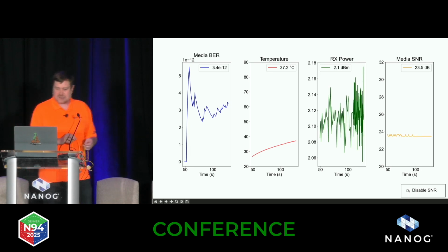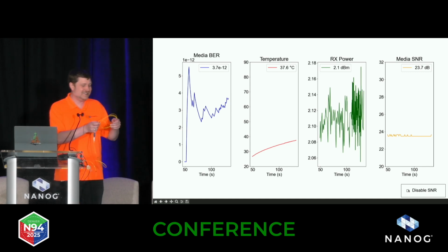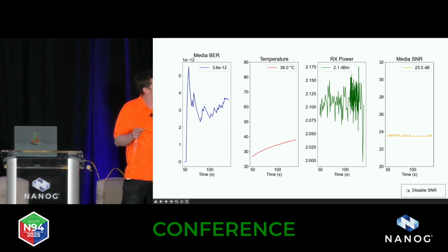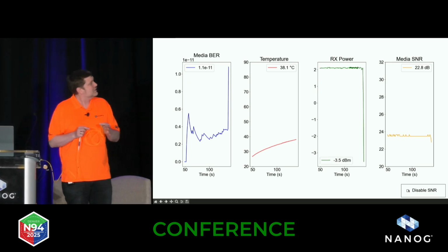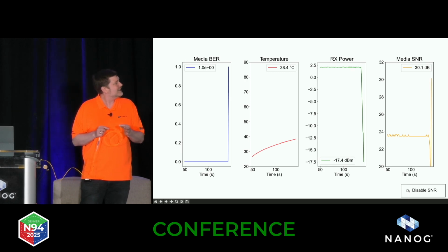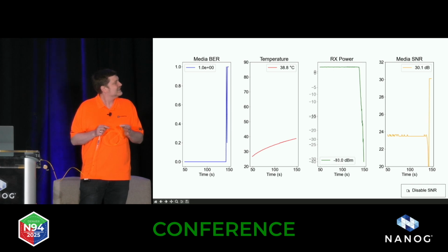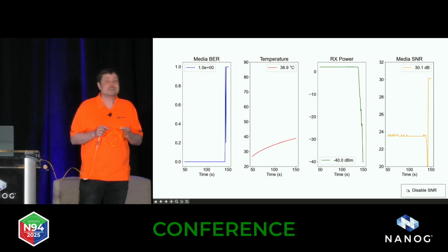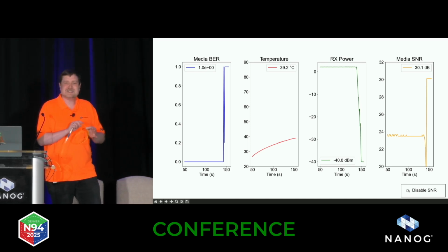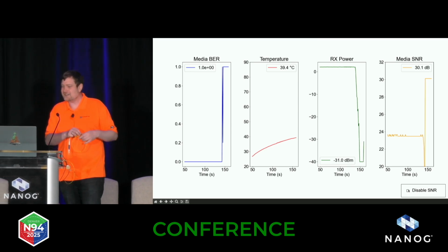And one more thing I want to show here, so you can see that this is not a pre-recorded video, that we do live things and interesting live experiments. Let me bend this cable and see what the consequences are. Oh, look at this. What is the minimum value you get here? Which is almost loss of signal. Any idea? Can it go beyond minus 40? Minus 40 is usually the value where you can say no signal, right? So I bent it too much, but it's all good. It's elastic, so it goes back.